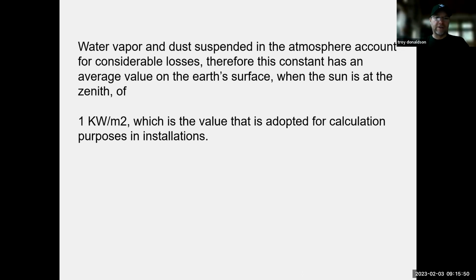So what I want you to calculate is using the footprint of your home, right? You don't have to calculate trigonometry to get the slope of your roof. You can just use the footprint of your home. If your home has a peak, then you get half of it. The other half's not going to be very valuable. It'll be pointing the wrong direction, right? So use the footprint of your home, divide by 2, and then we're just going to use 4 hours of sun. Okay. And on a sunny day, we get a lot more than that. But we're going to use 4 hours.